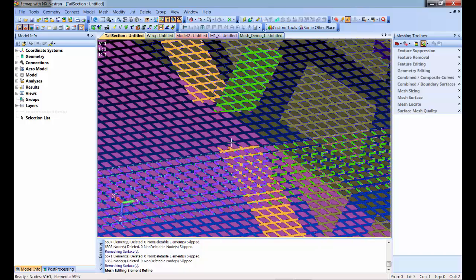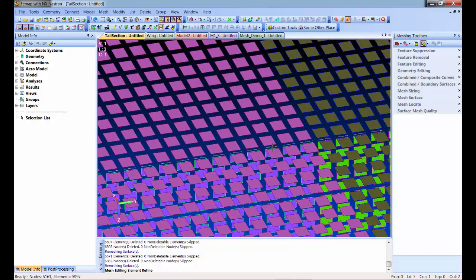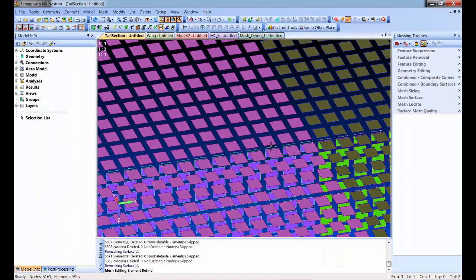There were beam little stiffeners around this model. It's splitting every stiffener. It's propagating pressure loads. It's propagating, like if you had a laminate definition, the material angle for the split elements matches the one that was the original element. Constraints, if there was a constraint between the two nodes, it would put a new one in the middle node. So you can now pretty much refine meshes instantaneously.